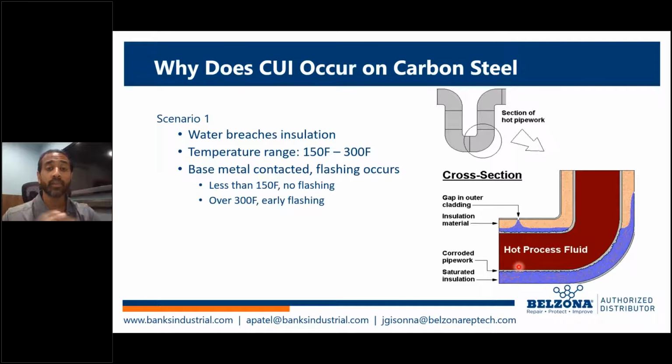In any kind of process situation, if you have something that is of a certain temperature, you want to preserve that energy and use it in another part of your process, because you want to keep your process as efficient as possible. And energy savings is always a target, especially for process facilities. So we wrap this equipment in insulation. And insulation, for the most part, is just porous. You put it around the equipment itself, and then you're going to wrap it in an aluminum cladding most times.